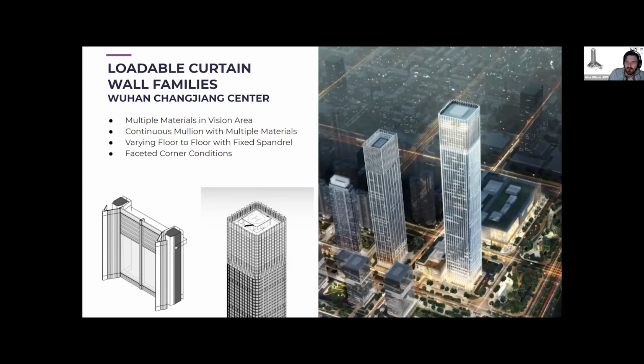This is all done just using basic loadable families, curtain wall systems within Revit with a division by length, and there is a varying spandrel condition, which is just a type parameter. It's a fairly repetitive building. So we just used Revit.